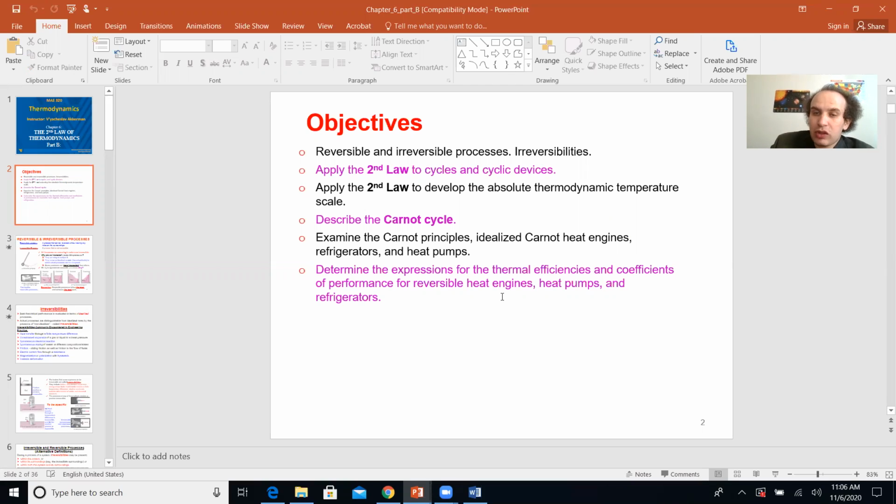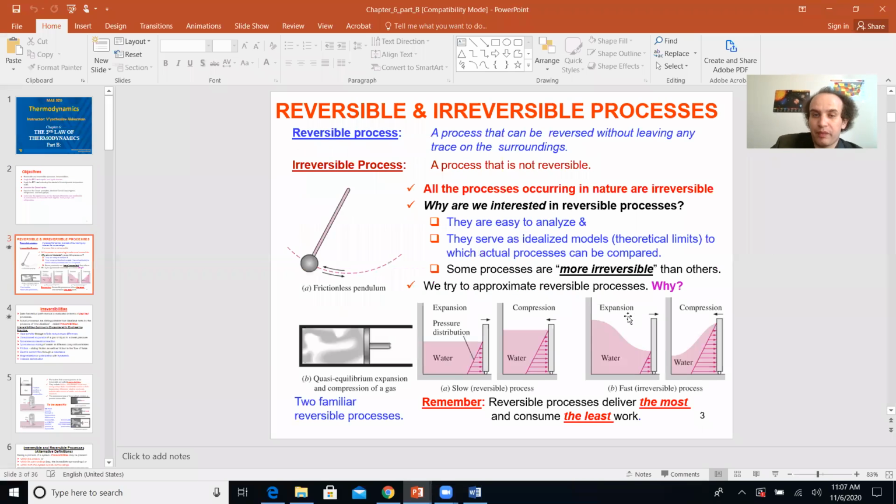Most of the processes we have, actually all the realistic processes we have, are entirely irreversible. So our next point will be how to measure irreversibilities, how to say what is more irreversible and less irreversible, what is better, what is worse. Because in fact, irreversibility is the penalty you pay according to the second law. So we want to measure whether it is a big penalty or a small penalty. That's what we're going to do. That's what we started last time, right?